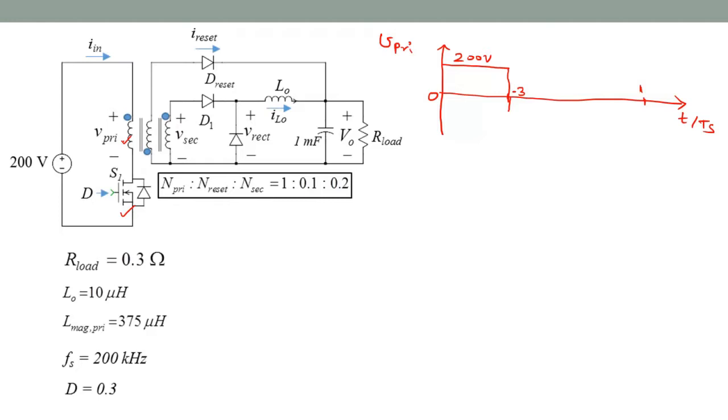The governing winding during the off interval number 1 would be this reset winding, because that is what gives us clearly what at least the reset winding voltage is. Reset winding voltage, if we define V reset with the positive at the dot and negative at the undotted end, then V reset during the off interval 1 would be, with the polarity assigned, minus V out, okay? Which we know is V out is 12 volts, minus 12 volts.